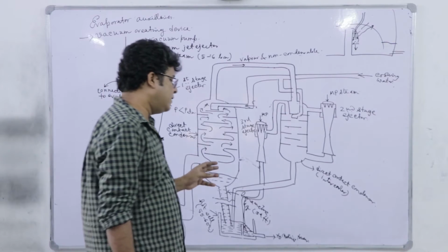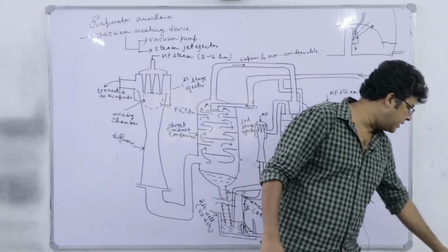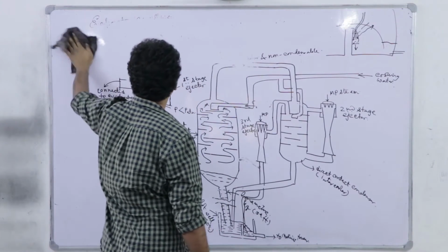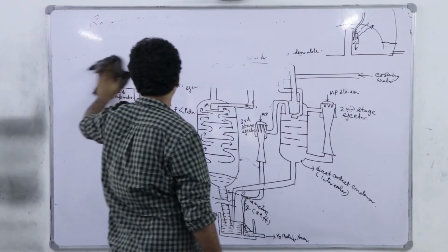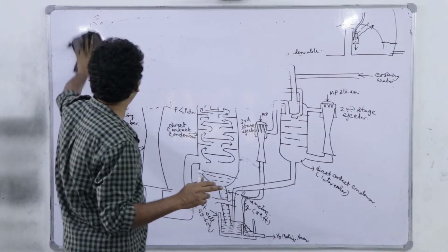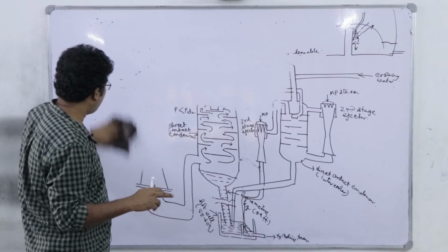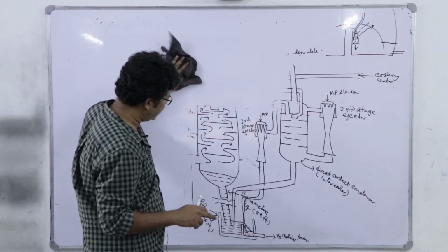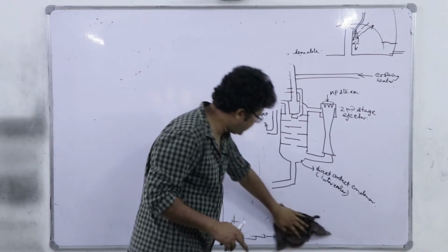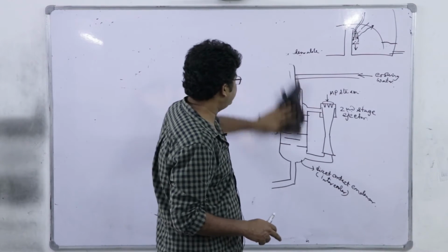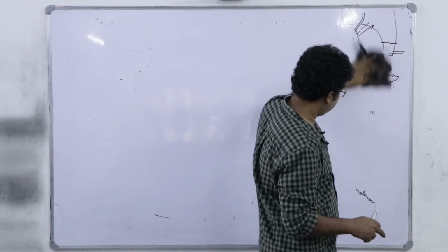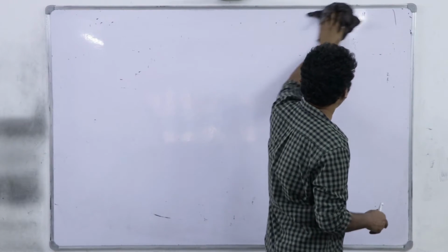Now next, as I have mentioned, in the condensate outlet of all evaporators, we must have a special type of valve called steam trap. So I will not go into the details of the steam trap. Steam trap is a special type of valve which will allow only the passage of the condensate, that is a liquid, right, without allowing steam to flow out. Okay. So steam trap, generally there are different types of the steam trap, mechanical, thermostatic, thermodynamic, etc.